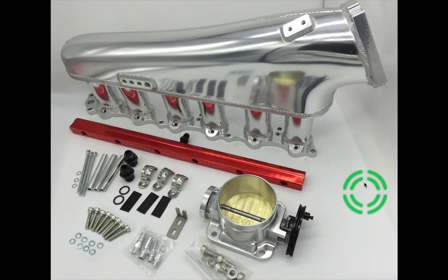So when you push your gas pedal in, it does not only revolve one, it revolves all 6 of them in a synchronized way. So all cylinders get the throttle body opened up, and the suction of one does not disturb the other one. So there is no turbulence. The air goes in a very direct fashion, that's how it happens. Okay, so that's about it for the intake.